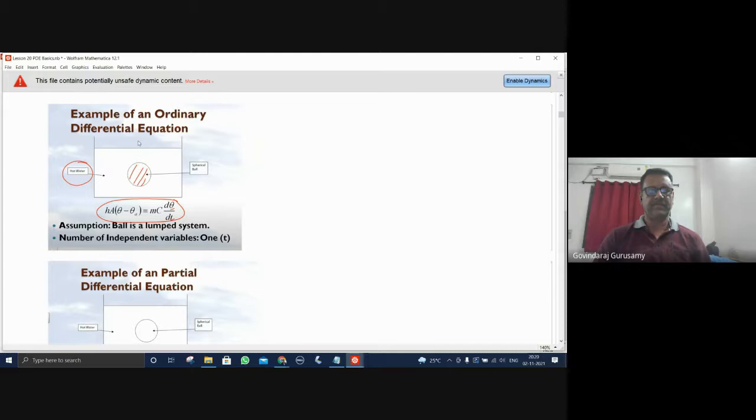If you go to the next case, same thing. If I look at it and make a comparison, you will see the difference between this and this. Many assumptions go into this, which means the bottom and the top are at the same temperature. There is no conduction considered. Convection is not there. There are many things that have been removed, assumed away, and then this equation has been found. With those assumptions, whatever result you get, you can analyze it. And then if you want to improve the system, you have to look for the other additional terms or additional effects to be considered here.